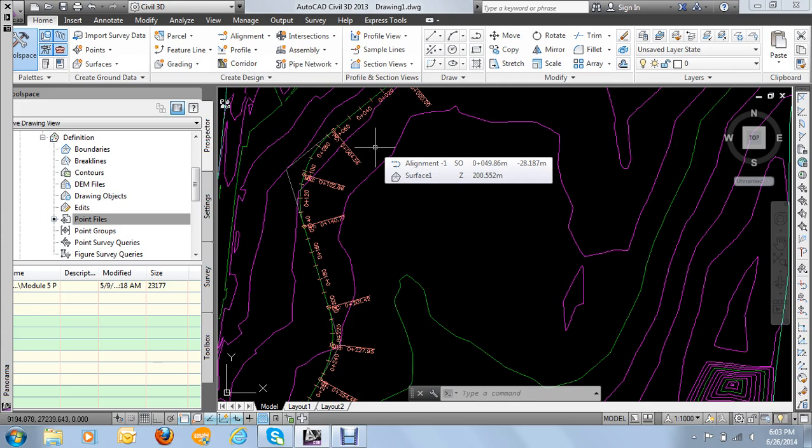So in order to design a road, you should have an existing profile, that is the profile created from the existing alignment, and then you have to design a profile that will pass through your existing profile, which will show the grades, elevation and station as usual.